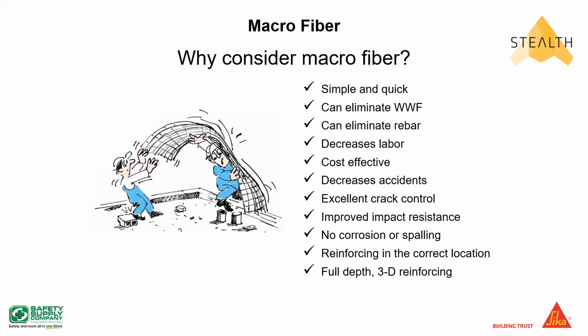Now, steel fiber can corrode, and there are occasions where we don't use steel fiber because of that, in wet areas and things like that, especially in the food industry. If we're doing a big warehouse slab in the food industry, or coolers or freezers, typically they like to stay away from the steel fiber.